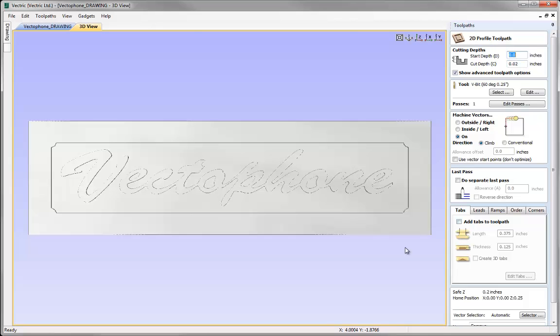Now if we just look down the bottom right here, when I go into this, you'll see that this part of the material is at 0, 0. You'll see that the Z option down here is 0. Now if we just move it over to where we are actually trying to use this toolpath, you'll see that if you remember we did actually do it inside the pocket, which was 3/64 of an inch deep.